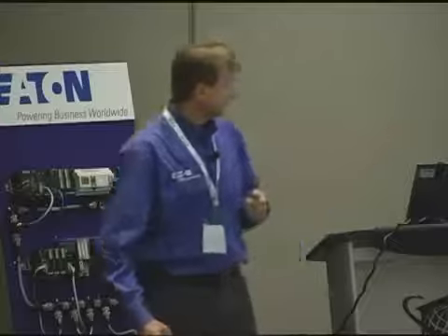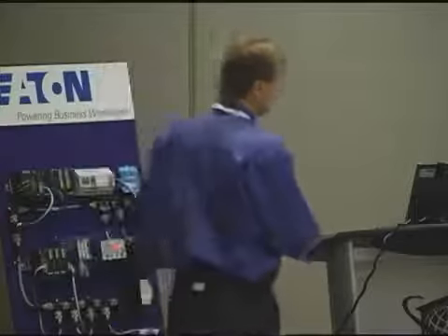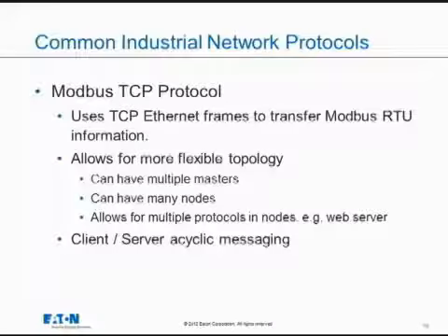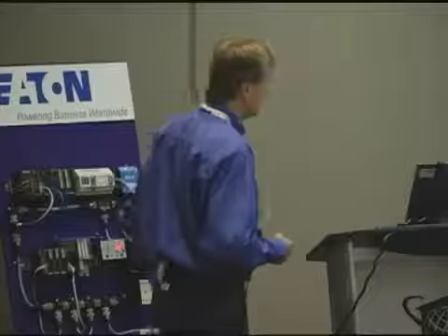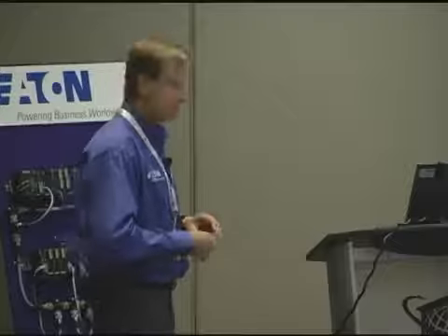It allows for multiple protocols. Now that we're on Ethernet, we can not only do Modbus TCP, some devices may have a built-in web server for diagnostics. That runs on a different protocol, typically HTTP. So we can run multiple protocols through the Ethernet network. Okay, again, more flexibility. Now, the way Modbus TCP works is it's a client-server acyclic messaging system. A client-server is another way to say master-slave. A client is the one that requests information, and a server responds to information.